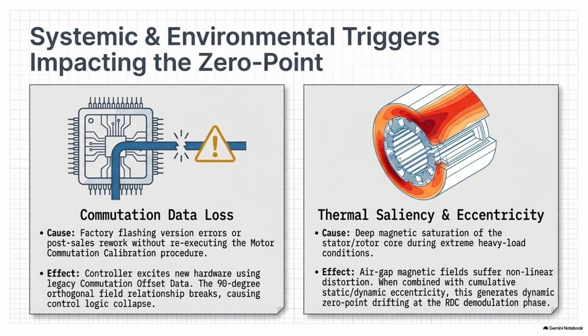So as the slightly less than perfect rotor spins, the air gap is minutely wider on one side than the other, and that wider spot rotates with the shaft. This non-uniform air gap scrambles the magnetic density, which feeds corrupted, skewed data back to the resolver to digital converter, or RDC. Okay. So the angle decoding gets totally skewed by the physical wobble combined with the thermal mirage.